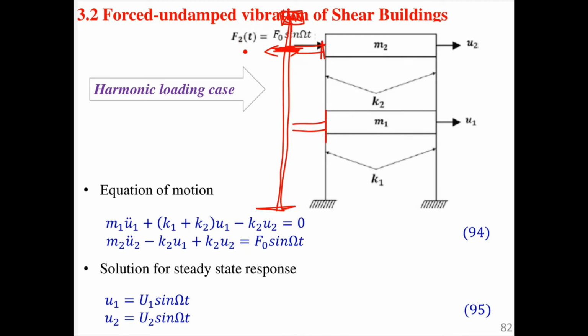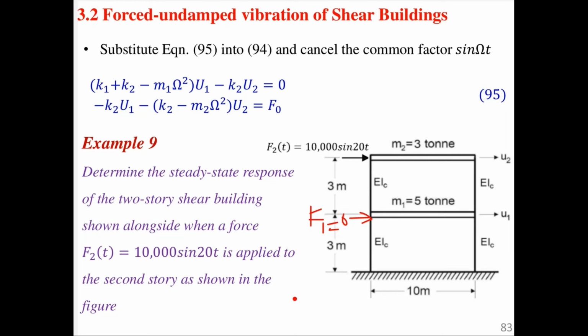So I'm trying to show you a typical scenario where we can have this kind of harmonic loading. That machine itself produces a rotary motion, and if it's out of balance, then there might be a motion in this structure, in the tower crane. The tower crane will then transmit the motion, or the forcing function, that will be experienced here, because it will be pushing this structure at uniform times, going back, pulling and pushing. That means we can get a uniform kind of motion being transferred to this structure. That's just for your understanding, so that you can see where we are coming from.